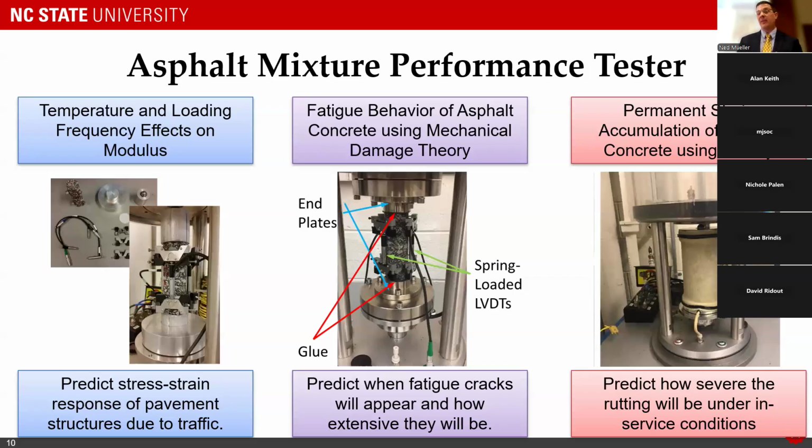And the third contribution is in looking at permanent strain accumulation. Now, in this case, we've defined some phenomenological theories and extensive characterization of the material to develop a method to characterize the material, the asphalt concrete, and then we can leverage that in the prediction algorithms to predict how pavements are going to rut over time, which again is a critical failure criteria to think about.